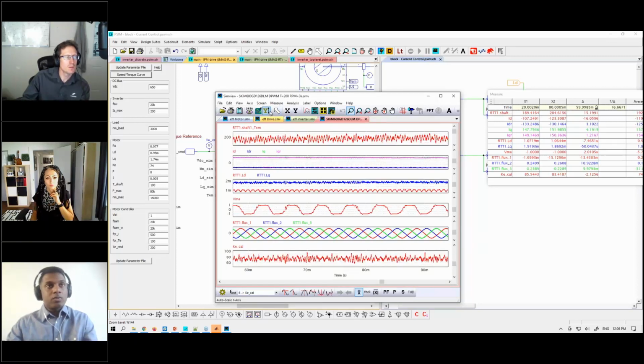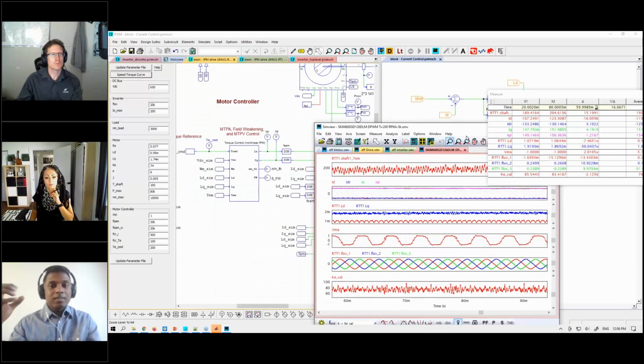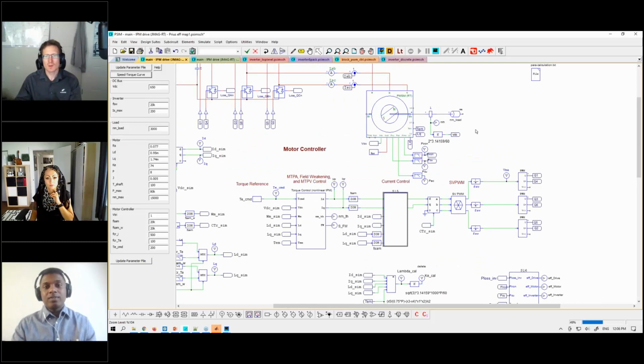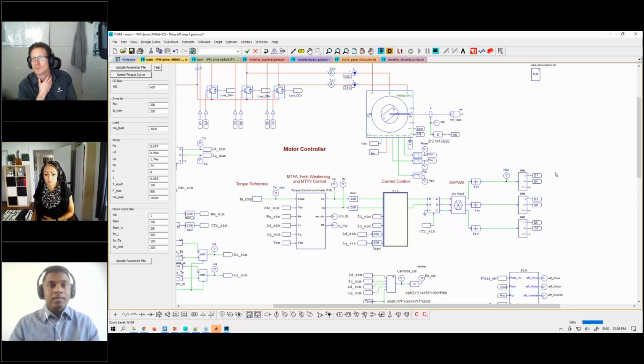The second follow-up question was that our measurements are incremental for both. Can I modify it to be an incremental value? No, because the simulation takes those specific operating point inductance values, and that's not based on what we can physically measure outside. That's the machine characteristic. But for the analysis part, if you do the efficiency map calculation, there's an option to choose which values you want to output, meaning either both incremental, both apparent, or D-axis being incremental.